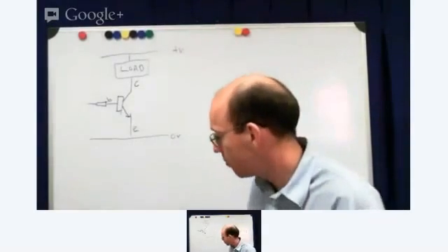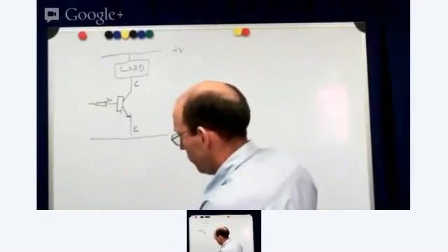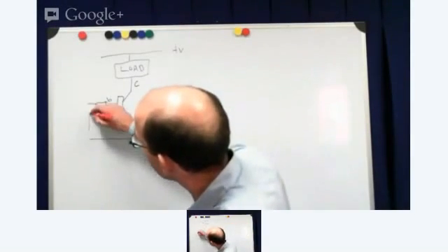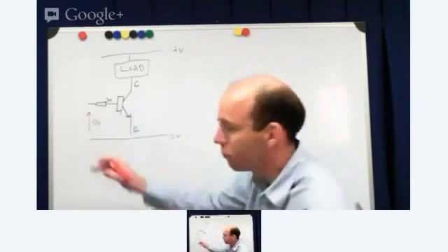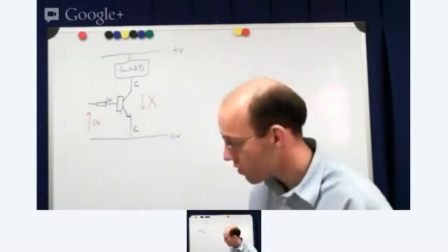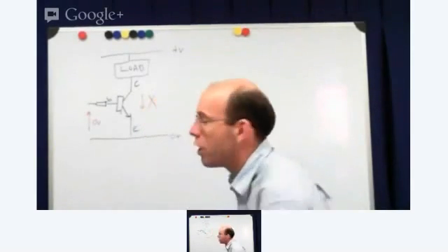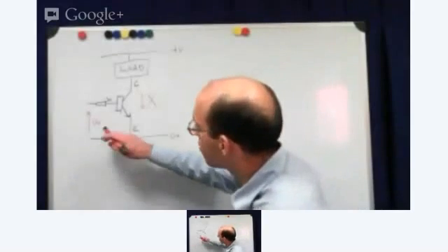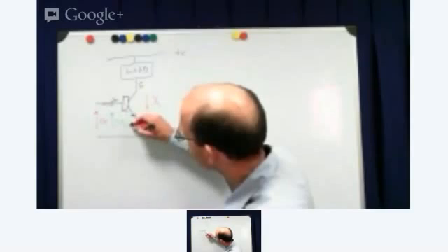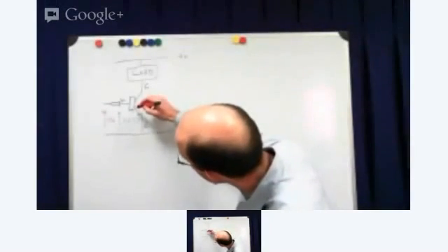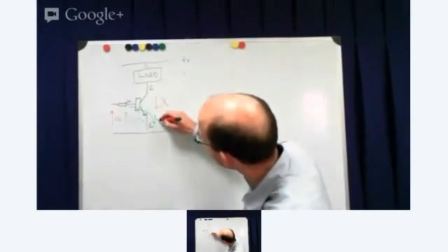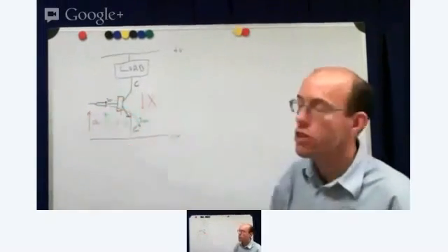So, how does the transistor work then? What happens if there's no volts on this pin here, so we've got 0 volts there, then no current is flowing down through the transistor. However, if we put at least 0.7, but we can put the full plus volts on here, so anything more than 0.7 volts on here, a small amount of current flows from the base through the emitter, and that switches the transistor on.